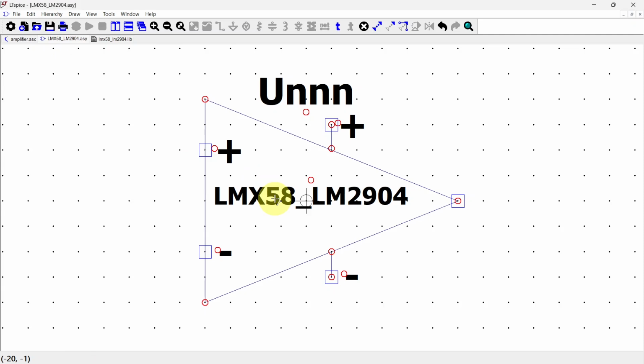The symbol is finished. By creating the symbol directly from the model subcircuit file, LTspice automatically handles the file linking for you. So you do not need to type an include directive manually as you may see in other tutorials.